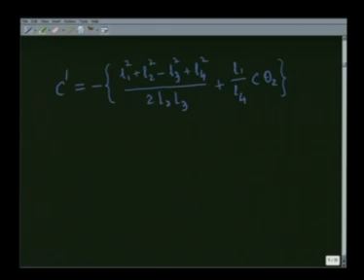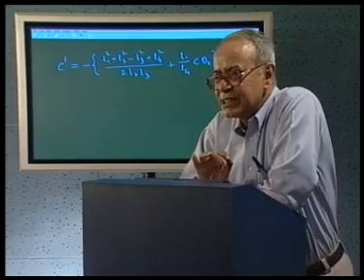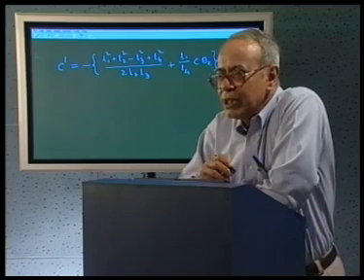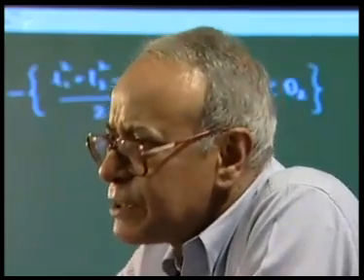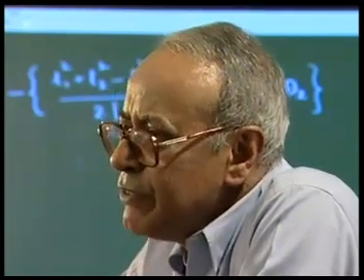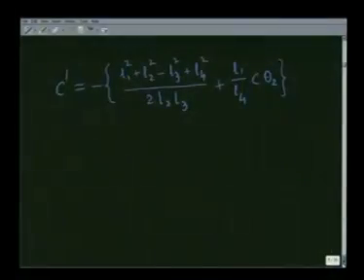The thing to note is that for the same set of given lengths and the same value of theta 2, we have obtained two values of theta 4 and two values of theta 3. This is nothing surprising if we remember that even by graphical method we would have got two solutions for the given link lengths and the input angle. This aspect is very clear if we solve the same problem by graphical methods.